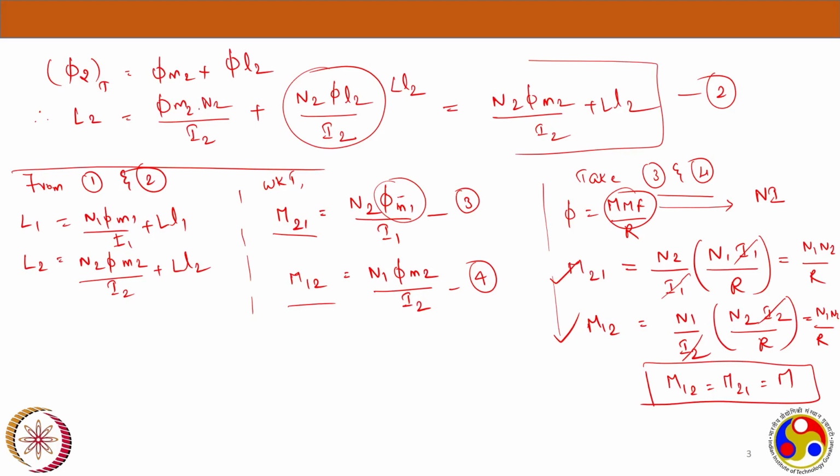Leakage inductance. How to write it in terms of Ni and reluctance? Leakage reactance comes from the air reluctance, right? You have to take the reluctance of the air there, and I don't think it links with any terms. Let's say for the same winding, if you have a winding N1, you know the turns ratio N1, and you have to actually calculate the phi L2, that is the leakage flux.